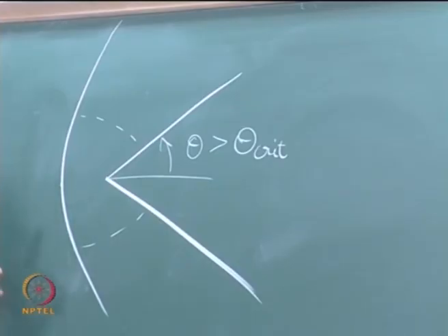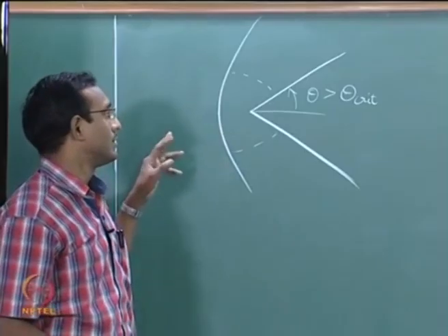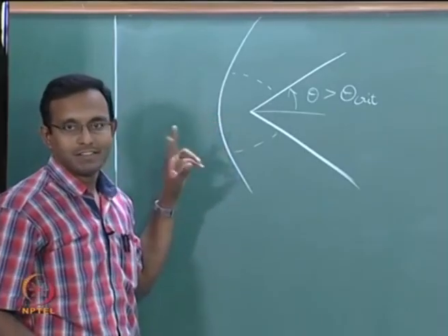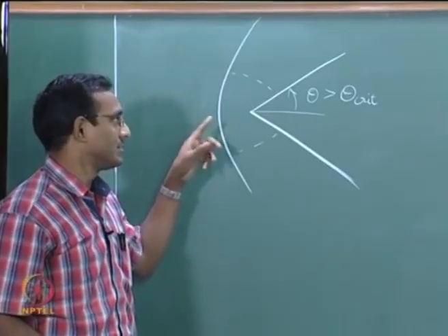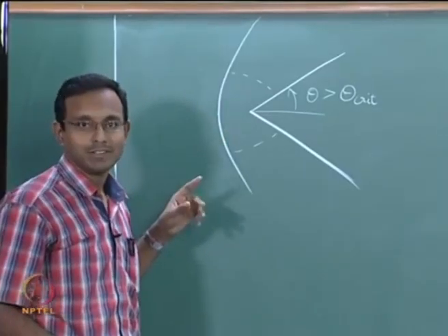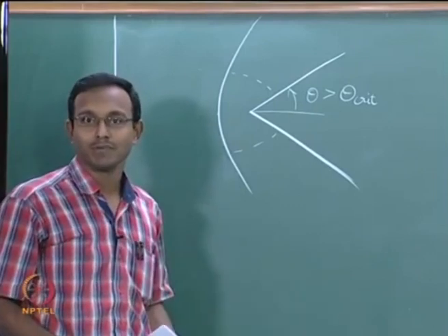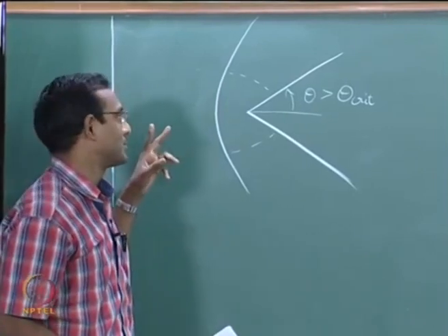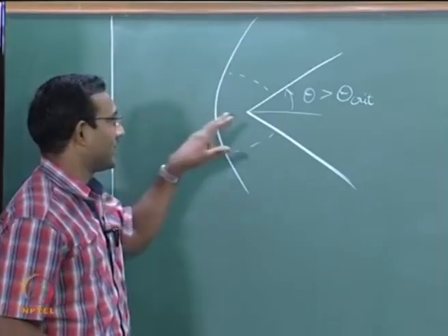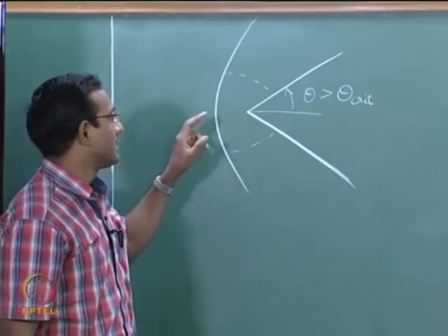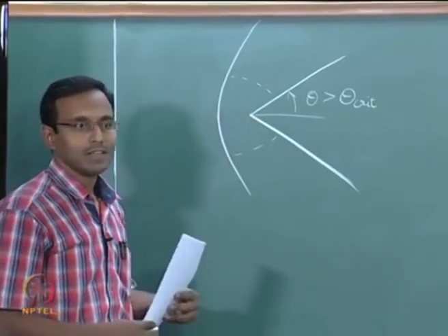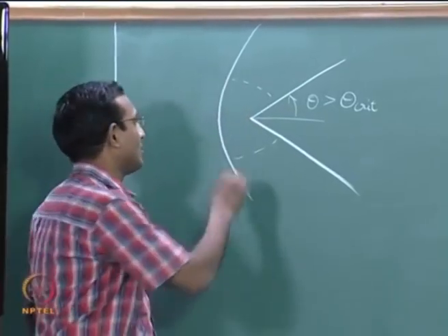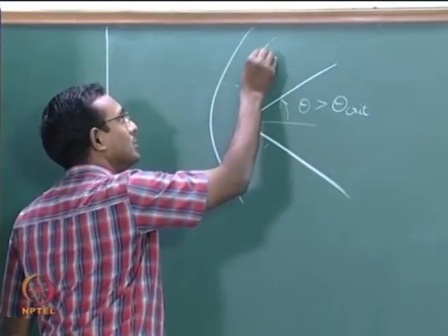And then we said if the gas becomes more compressible, I gave an example of gamma less than the previous gamma. If gamma decreases, then it is roughly more compressible. That is not the only way to make it more compressible, that is one of the ways. If I decrease my gamma, the flow has a possibility of having this as an attached shock. There is also a possibility of it just decreasing to some other bow shock